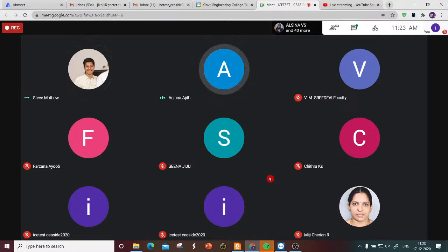How can the split tensile test be conducted on cube specimens? Ma'am, just for knowing the value. Ma'am, for split tensile strength, we will be using cylindrical shape, and for the rest, we will be using cubical shape.